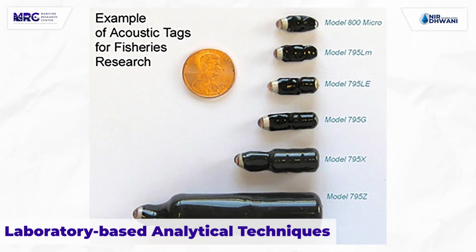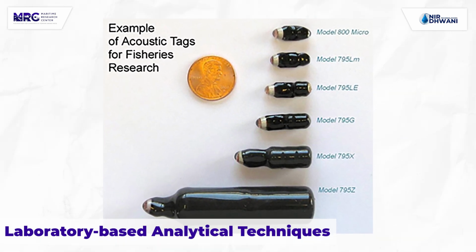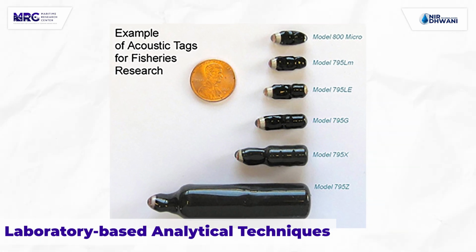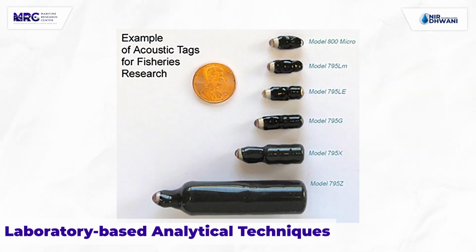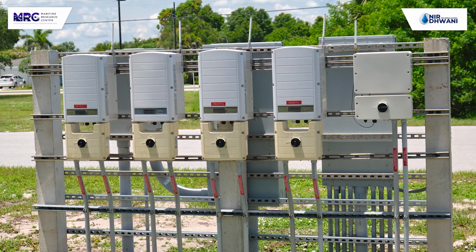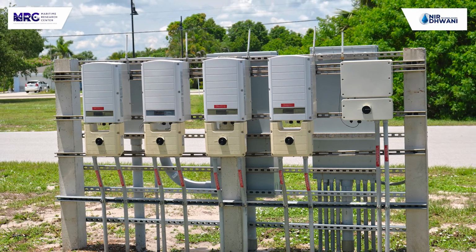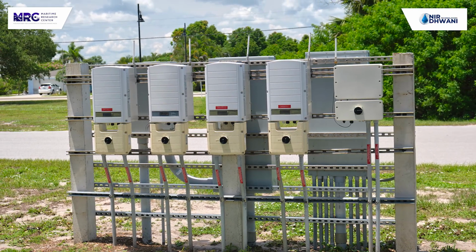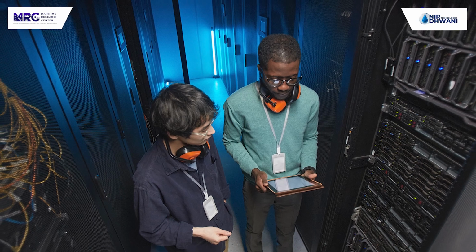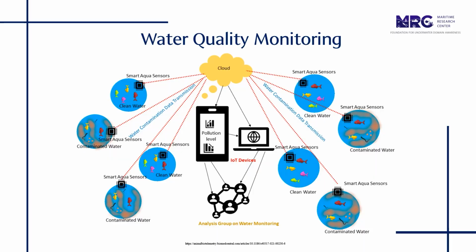So we can have something like an acoustic transmitter tag with a water conductivity and temperature sensor, which would be able to quantify the different water qualities. This tag would be based on an ultra low power mixed signal electronic design similar to an acoustic tag platform. Then we could have sensor integration, onboard data processing and storage capacity. So a proper data infrastructure can be built up in order to collect data, store data, analyze it, and then share the results with the various organizations in real time.